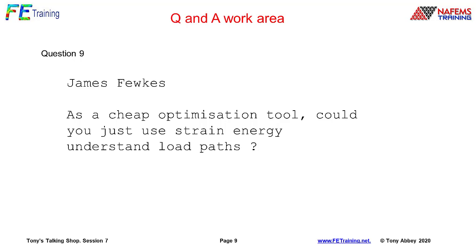You're essentially doing an evolutionary type of approach. Now you have to do a bidirectional, so what you say is, whoops, I'm going down that path, I'm locked into that path. As the load path is changing, maybe this configuration would give me a better load path. That's when the bidirectional, the BESO method, comes in to say, let's back out of that. So as a simple approach to explore what's going on, I think it's a great method. And if you can set yourself up a little macro to go through a couple of iterations, then I think it could be very, very useful. That's how I like on the course to introduce topology optimization, because we can understand removing inefficient structure by an evolutionary type approach.